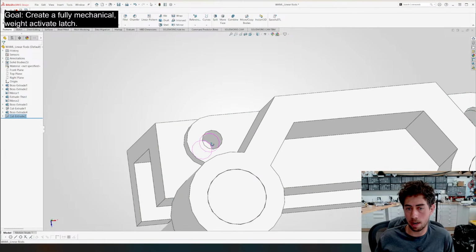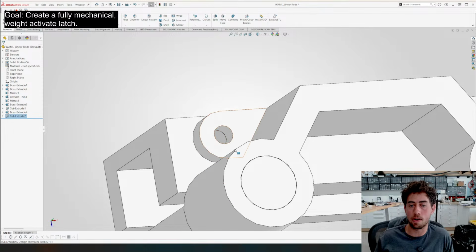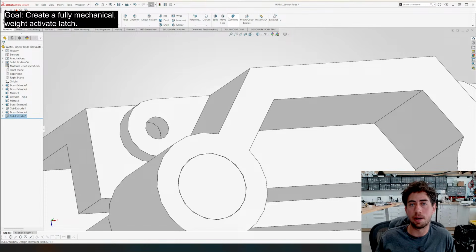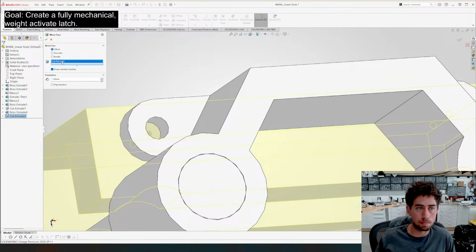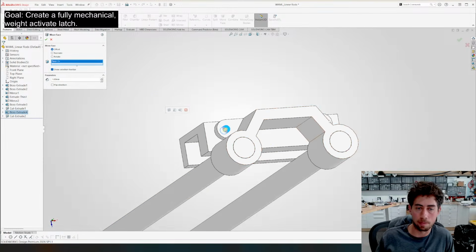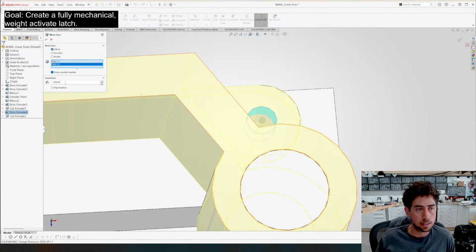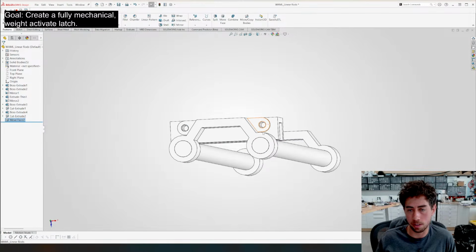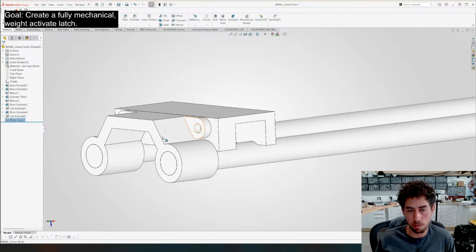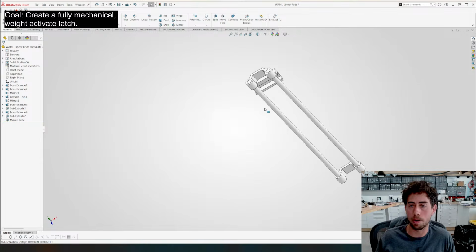And then, so here's what I mean. So right now they're the same size. And so if I forgot to change this, I would just drill them out. But I didn't forget. And so I'm just going to move the face on these holes. And they're going to be clearance holes. And 0.35, other way. And now we got a clearance hole. So I'm going to screw through this into this, and then it's going to be one part.